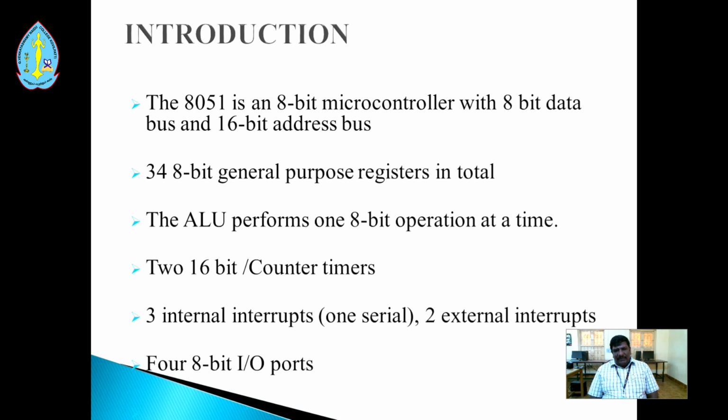It is an 8-bit microcontroller with an 8-bit data bus and a 16-bit address bus. It has 34 general purpose registers in total. It has an ALU, called the arithmetic logic unit, which performs 8-bit operations at a time. It consists of two 16-bit counters and timers and 3 internal interrupts: one is the serial interrupt, and the other two are external interrupts. It consists of 4 8-bit I/O ports.